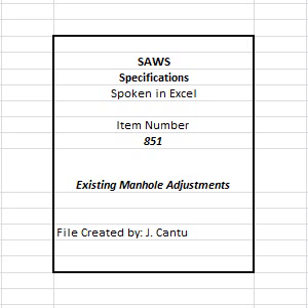7. Manholes shall be adjusted after the street's base material has been laid and before placing of the final surface course. 8. Manholes that are planned for adjustment on an existing surface course, not planned for replacement, will be in accordance to the City of San Antonio Utility Excavation Criteria Manual Standard Drawing No. 8.8, but must first be directed by the engineer. 9. All manholes shall then be raised or lowered a sufficient height so as to be level with the finished surface course. 10. Adjustment in height will be made by the addition or removal of throat rings above the manhole cone.